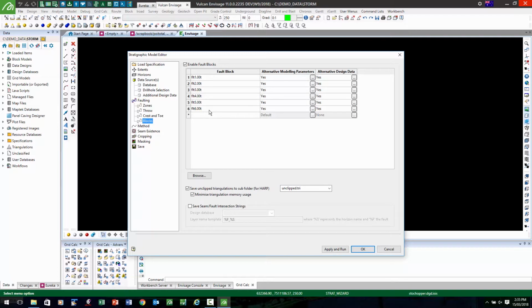block faults as your fault domains. And they were very good in that they gave you a lot of flexibility. You could define your fault planes with as much detail as you required, handcrafting sections or projecting lines, however you wanted to do it. If you had to weave your faults in and out of myriad borehole intercepts, you could do that. And then make a solid, chop the planes up against the solid using something like the multi-boolean tool to make mutually independent fault zones which you could then use through the entire integrated strat process from fixed map to the modeling to the hard model.